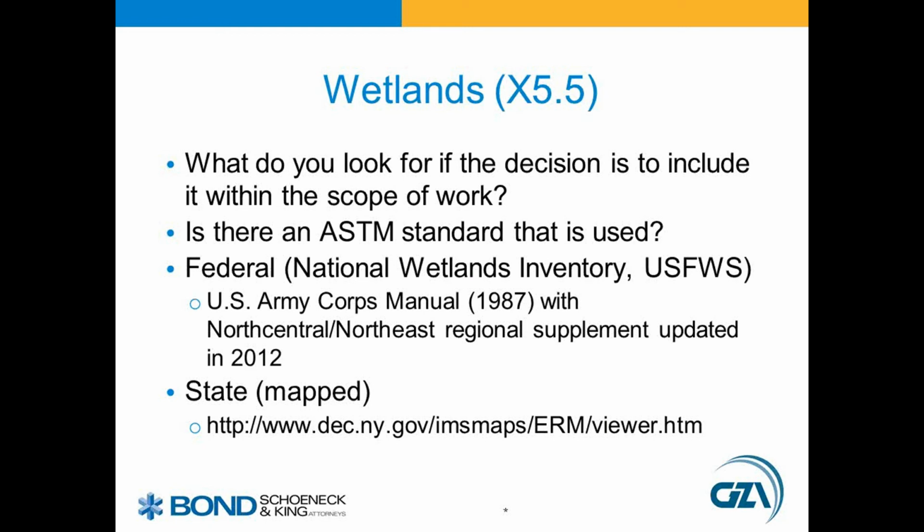ASTM used to have a standard. It was withdrawn in 2007 because it wasn't updated within the required time. Because of that, we rely on the U.S. Army Corps Manual, published in 1987, and subsequent regional supplements. The one here in New York would fall under the North Central Northeast Regional Supplement, which was updated in 2012.